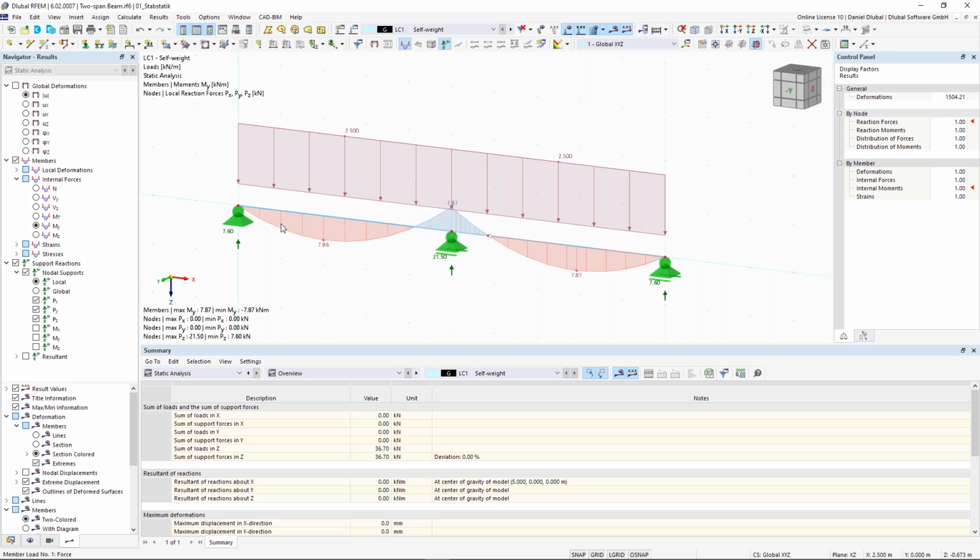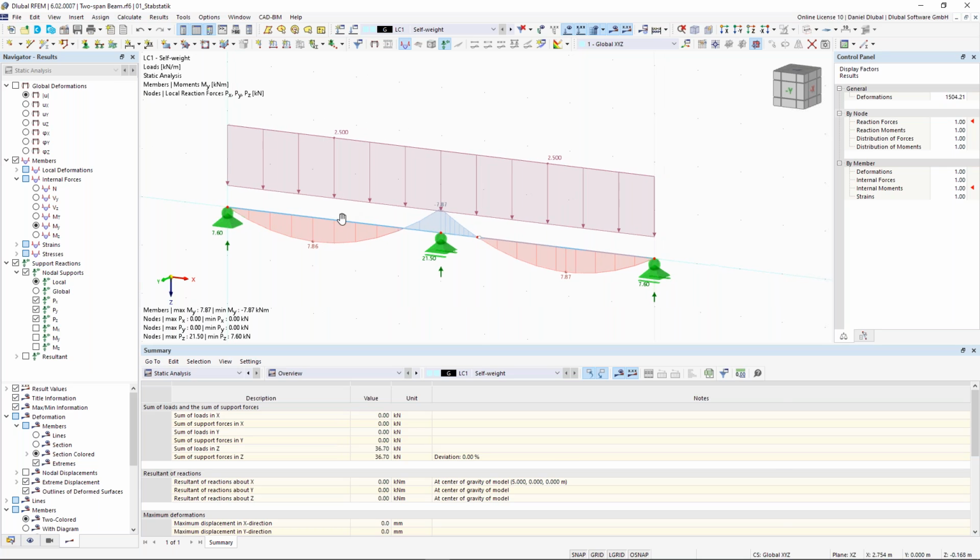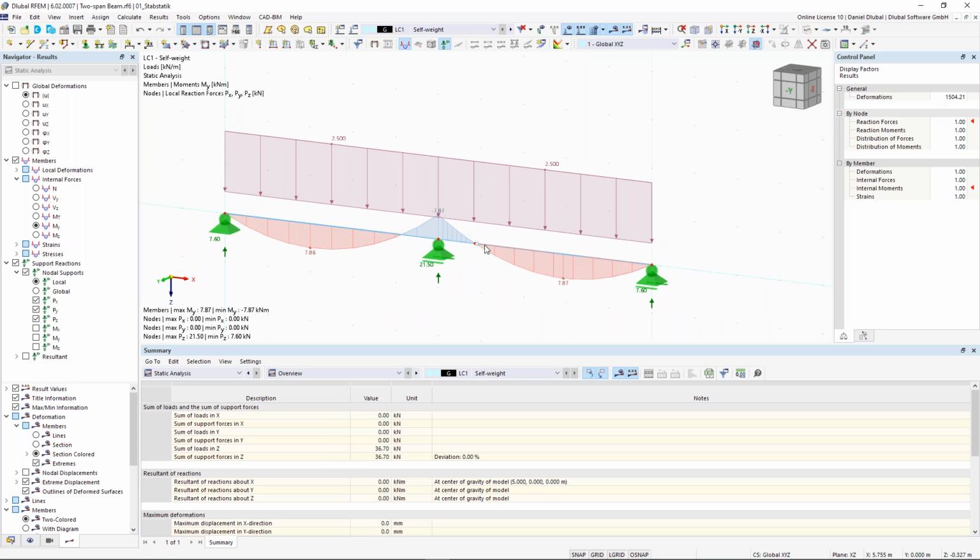The previous beam had one degree of freedom free, so when you calculate it with the force method, you need to find this undefined value, and with this hinge we make it statically determined, and this is a huge advantage. So yeah, let's continue with the poll.